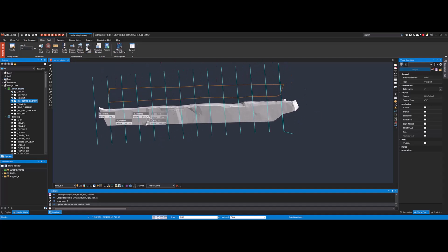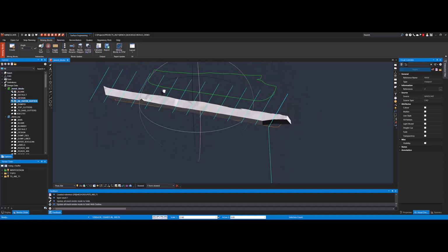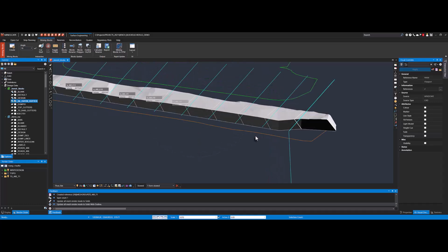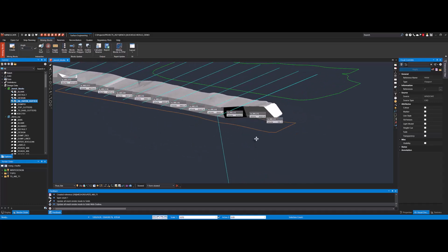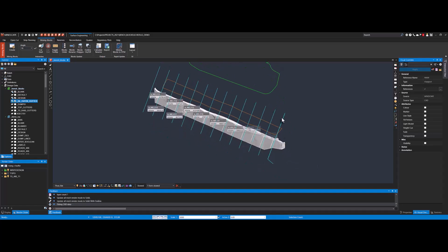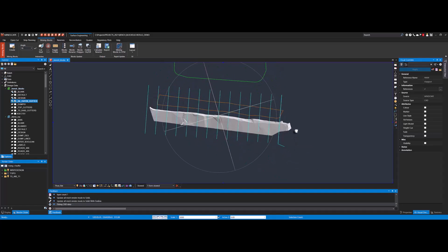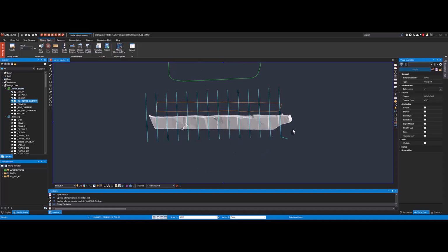Once you're satisfied with the results, simply end the cut operation, and the final geometry will be written directly to the mesh folder. This ensures your updated mining blocks are stored and ready for downstream processing or reporting. Additionally, these bench blocks can be reserved, allowing you to maintain control over areas that are already accounted for in planning. During this process, the calculated volumes are written to each block as metadata, preserving detailed information for later use in scheduling, reconciliation, or production tracking.